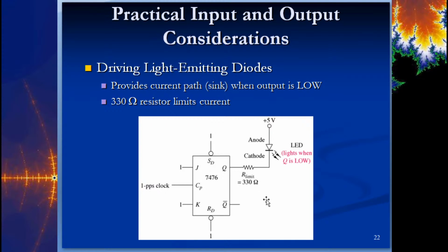If you had your own, let's see, is there any that you can, yeah, there is. On your DE10 Lite, you've got 8, well, those may be input ports. No, they're I/O. So you can make them output. So my whole point in that is that if you want to, you could set up your DE10 Lite to blink a light out of one of these flip-flops. I don't know, I might mess around with that and see if I can figure it out. I haven't tried it yet, but you could. And just do a simple little blink here, because all this is a 1 pulse per second clock. You could put that in Quartus if you wanted to.